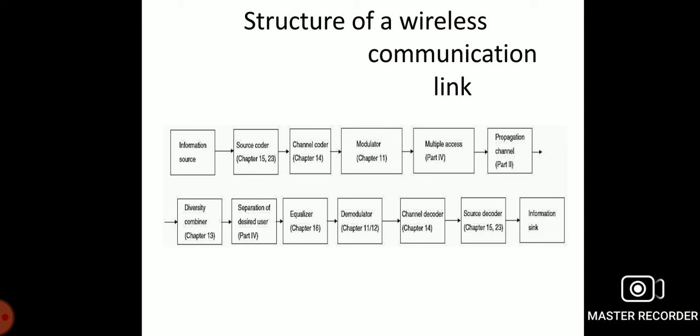The source, the analog channels with the filters, amplifiers, up converters and also the down converters, and all the sub modules or stages are equivalent to a time-discrete low pass channel unit. The goal of this mathematical link is to analyze the modulation format. The parameter used to judge the quality of the modulation format is the bit error probability.